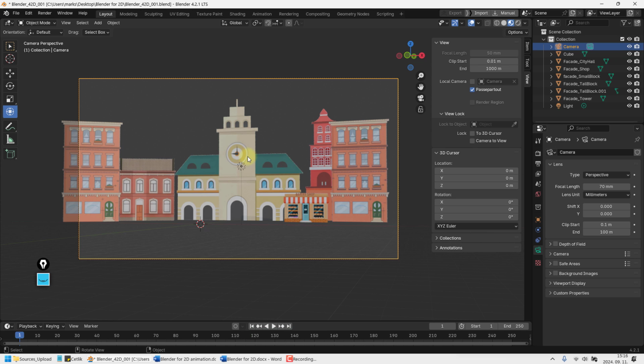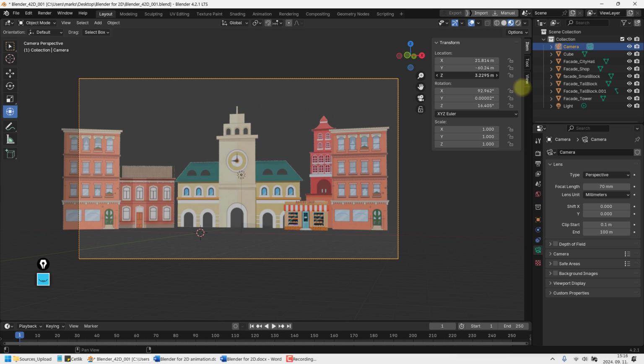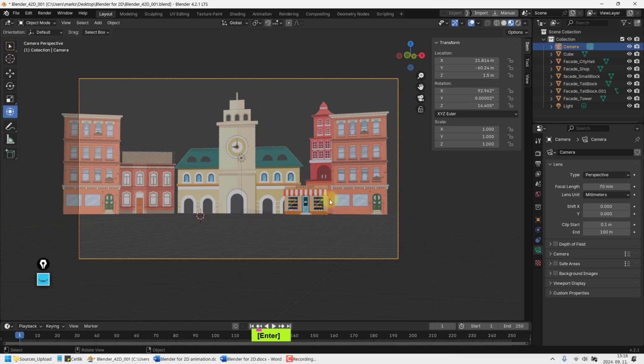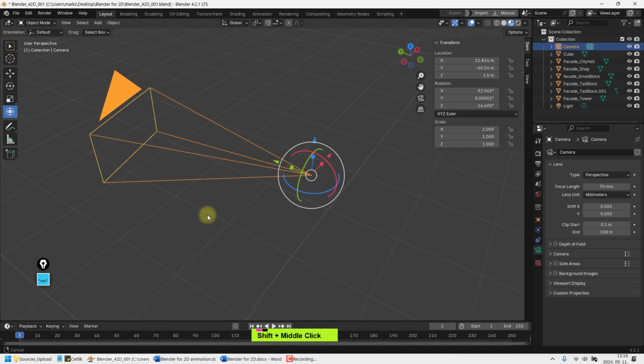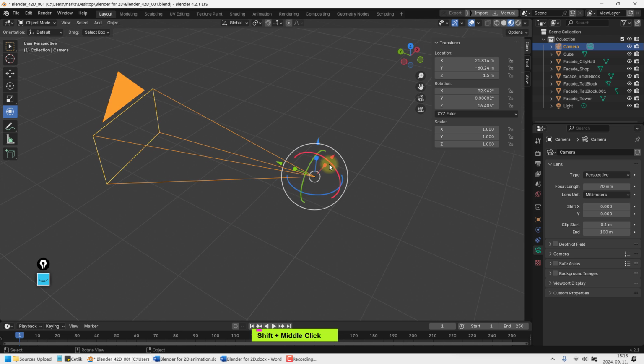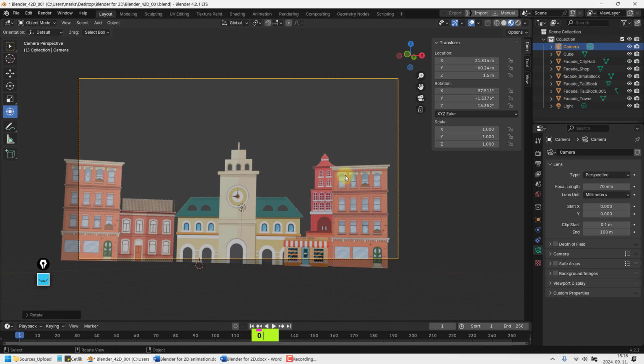And working on a composition. Now, the camera position is this. So the camera is selected, and the normal height is 1.5 or 1.55. Now, if you adjust that, but your composition is off because the camera is showing too much of the ground, it is a free camera. So let me leave this and show you that this camera is a free camera. It has no target. So every move that you make is basically happening through this position. So if you make a tiny move here, it will be a lot of change on a scene.